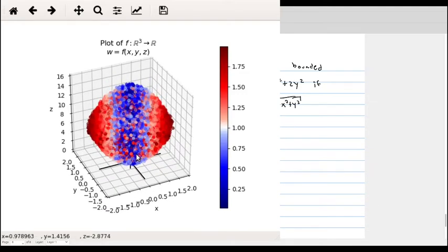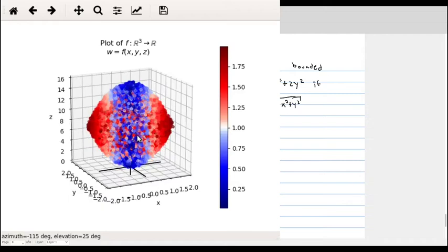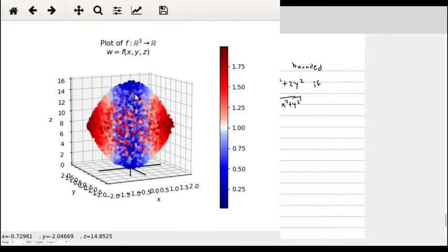you see very clearly that in the middle of this object, the center of this object, you have the lowest mass density, and as you move closer and closer to the boundary of the object, or you get further and further away from the z-axis, the mass becomes more and more concentrated as you move out towards the boundary of this object. So the idea here is we want to directly calculate the mass of this region with a distributed mass density.